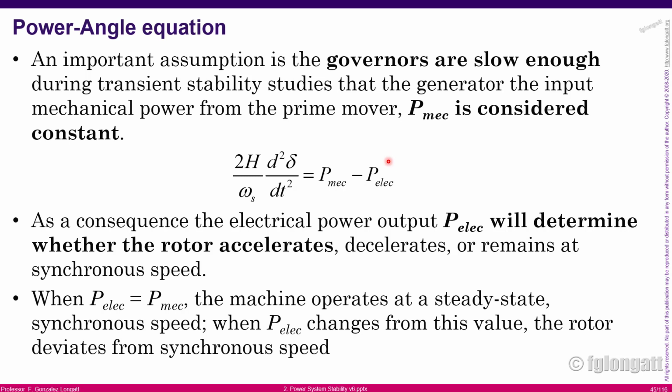In real life, the governor is acting, however, the action is probably negligible, especially if we are working with very big generation units with a lot of inertia. But if we were working with very small, isolated systems with very small inertia, please don't take for granted that the governors are not acting, okay? If you are working in a very small village and there are two or three diesel generators working together, please be careful, okay?